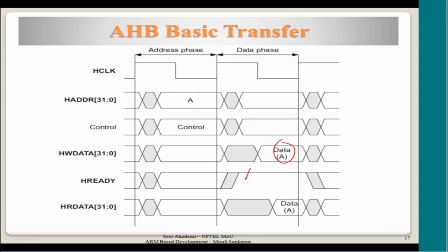Once this goes high, in this clock cycle, when it becomes low, the data is made available and the memory can fetch it during this time. It will take the data which is available on the bus, and then it will bring down this value. If it happens to be a sequential access, maybe it will continue to hold it and read the other data, which I will show you later.